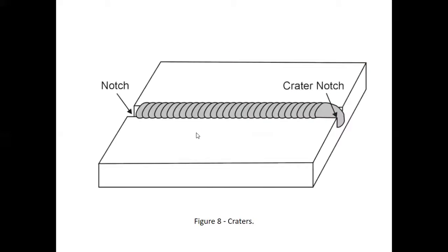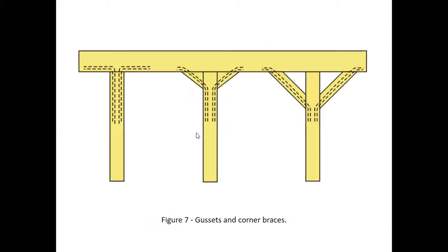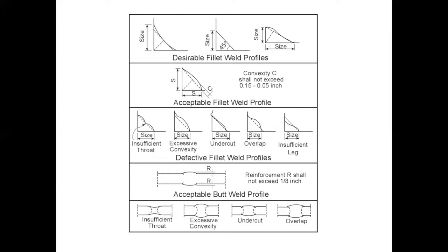So, we're going to look right here. And what we have are a couple examples of some things that aren't the best in welds. So here on this left side, we have a multiple stringer fillet weld. Now it's probably 3 stringers went into that fillet weld. We'll have 1 on the inside, 2 on the outside.